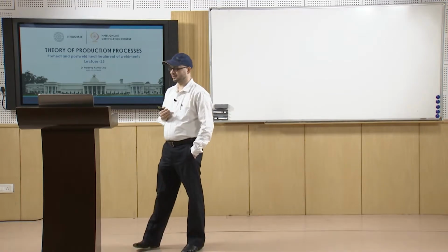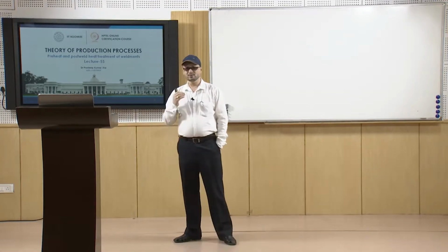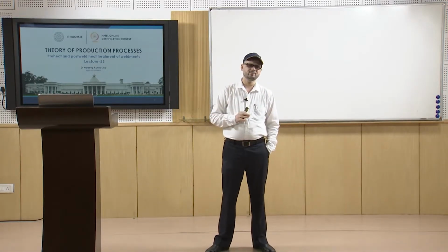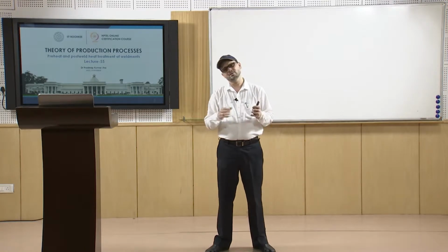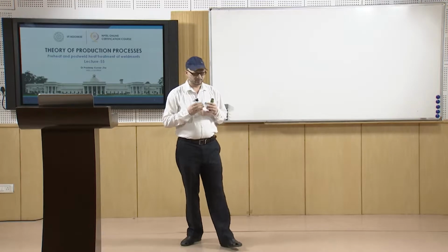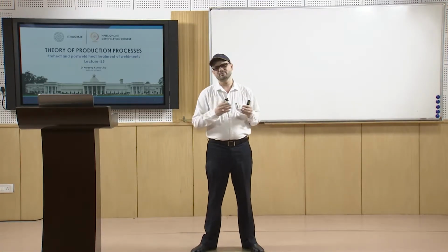The need is felt because if you do not pay proper attention to preheat or post weld heat treatment, then undesirable phases may occur. There may be brittle phases, and there may be cases of stress corrosion.